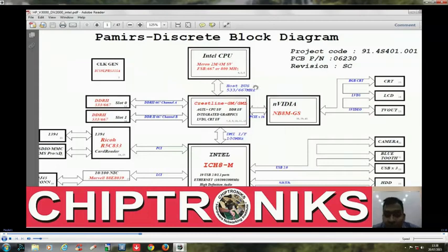There are no pins across this IC, so you cannot test a BGA chip. You can only test a BGA chip at its output, at its connector. So these are connectors, and they are controlled by their controllers, and the controllers are present in this. This memory controller controls the output at this slot. The display controller controls output at this connector: CRT, LCD, TV out.